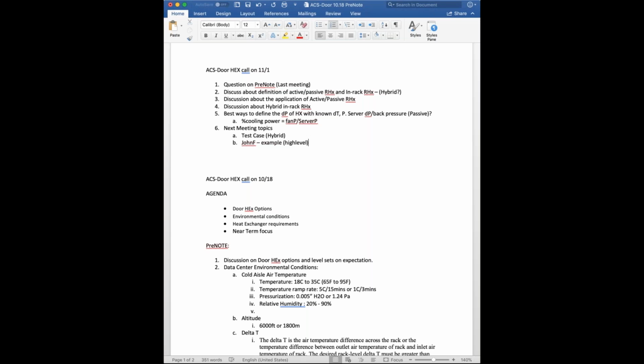I know what you're going to say, but if you look at the server, the room for airflow in the server is so minimal compared to the coil that the pressure drop within the server will be maybe 90% compared to 10% in the coil, because the room for airflow in the server is almost non-existent.